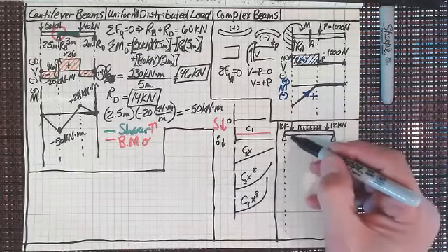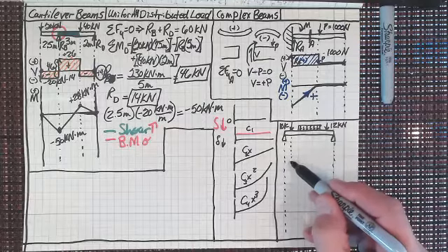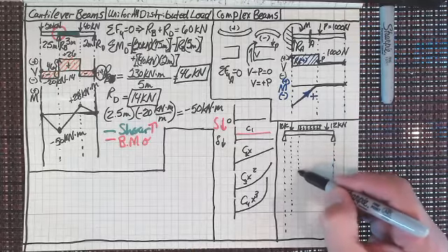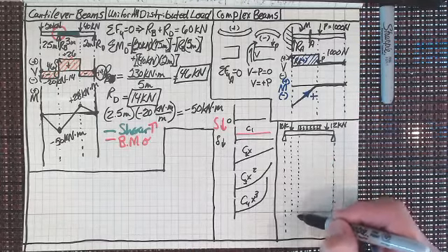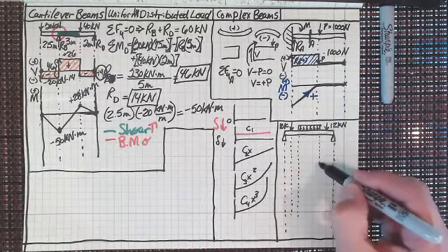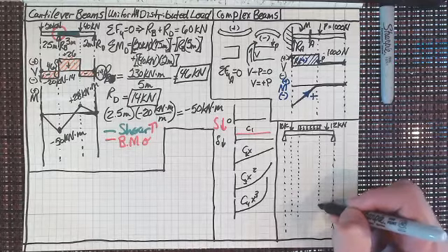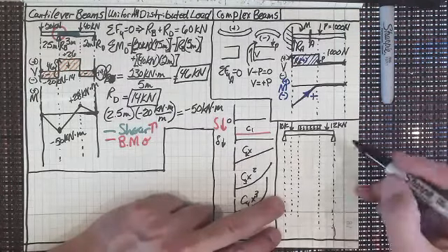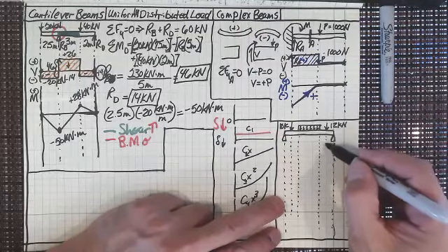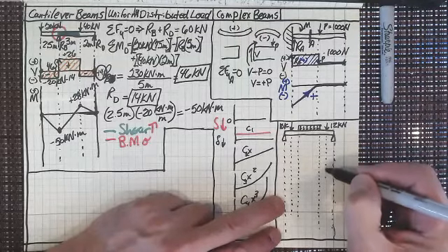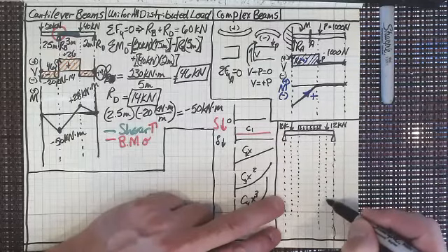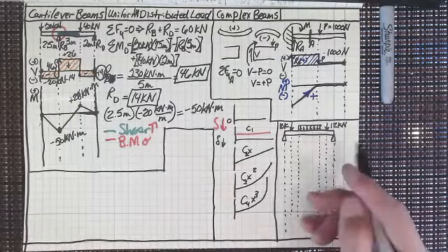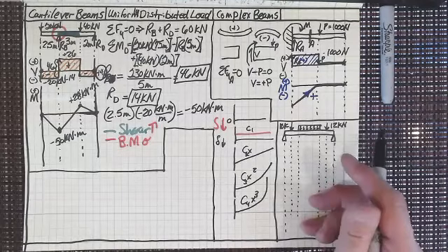Now, let's drop some of these lines down that are going to be critical for our shear force and bending moment diagrams too, and you can see that there's a lot of them. The reason that I wanted to look at this uniformly distributed load is because this really enters in a more realistic way to how beams are loaded. A lot of the loading in a beam isn't somebody stacking a refrigerator in one part of the floor or something like that. It's really the building materials. And so the building materials are in some ways uniformly distributed over the load. And that's what we'd want to look at.